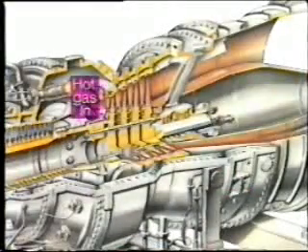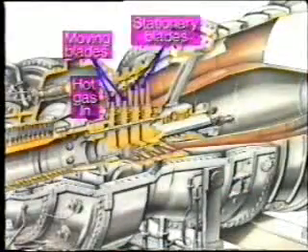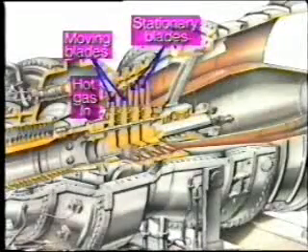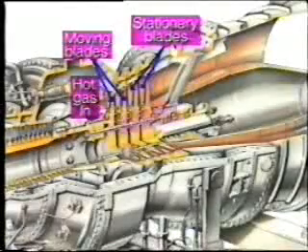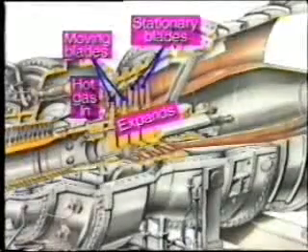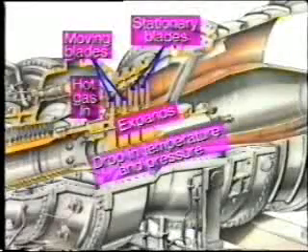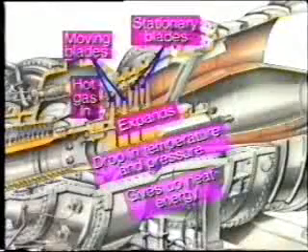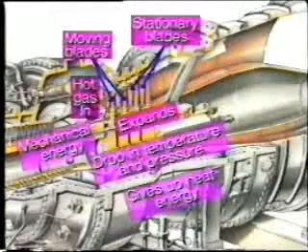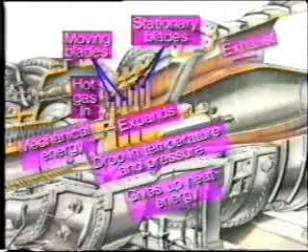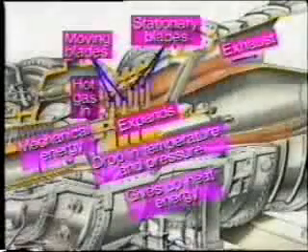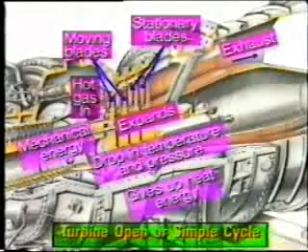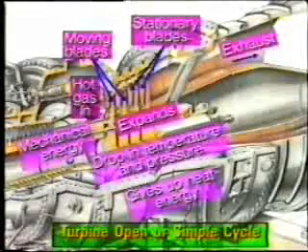In the turbine, hot pressurized gas passes through a series of stationary and moving turbine blades, and this causes rotation of the shaft. The hot gas expands as it passes through the turbine, and this brings about a drop in temperature and pressure. The gas has given up heat energy and converted this to mechanical energy in the turbine. The gas is finally exhausted to atmosphere. And for this reason, this process is known as the open or simple cycle gas turbine. There are other cycles, as we'll see.